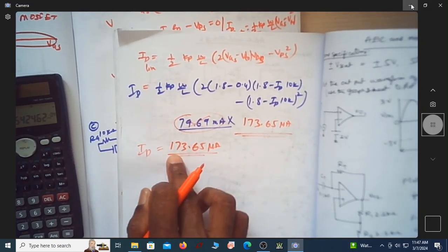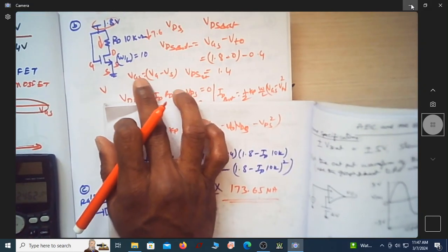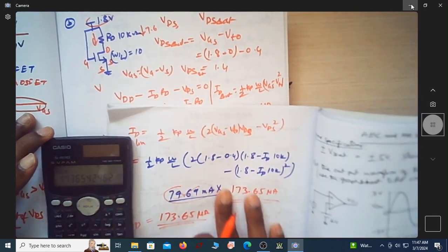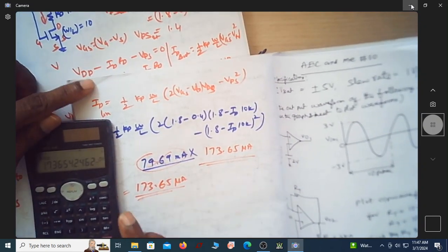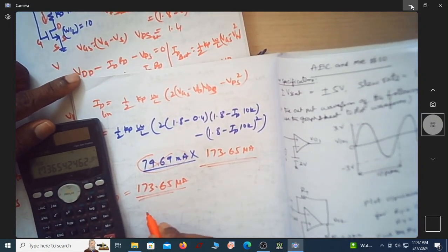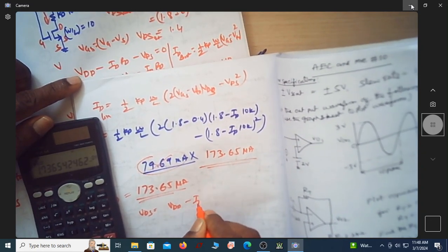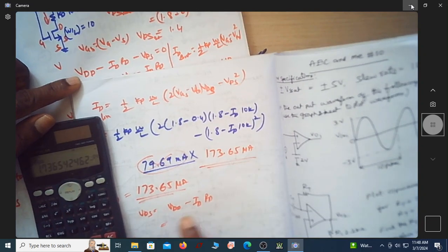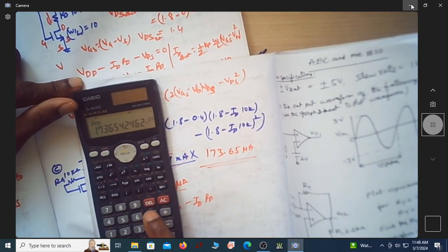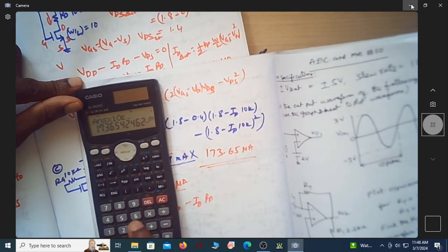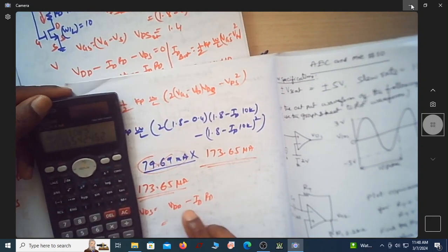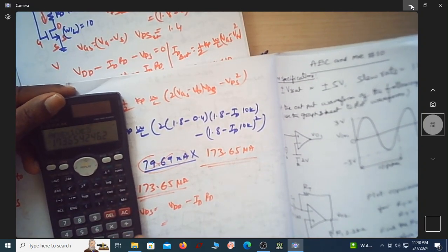If this current is flowing, is it consistent? So is this circuit consistent? You can find out that. If this is ID, then what is VDS? VDS is equal to VDD minus ID into RD. So it is this current into 10 exponential 3 is the drop. Okay, equals.